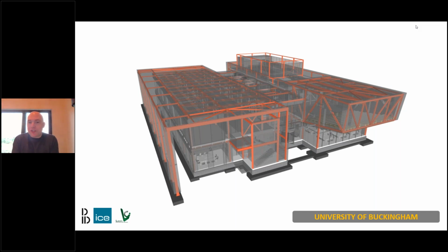So what we ended up with was actually a more efficient structure. We could use some of the residual capacity within the foundations of the columns that support the cantilever. So we didn't need any additional concrete in the ground. We didn't need any additional excavations. We didn't need to close the redway. And we actually looked at an overall reduction in the amount of steelwork within that building by achieving the cantilever detail.